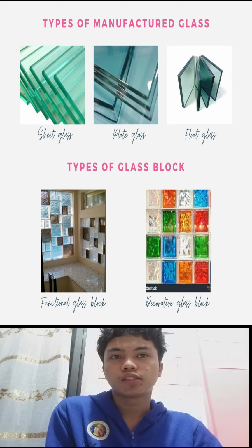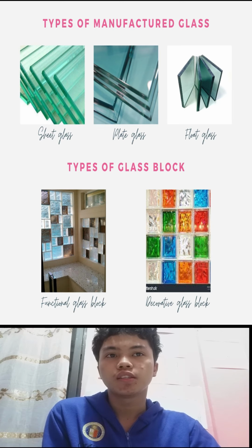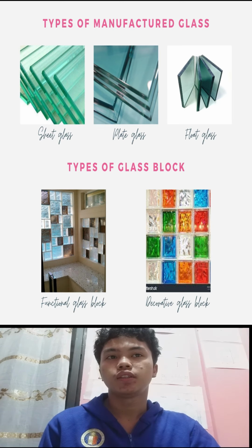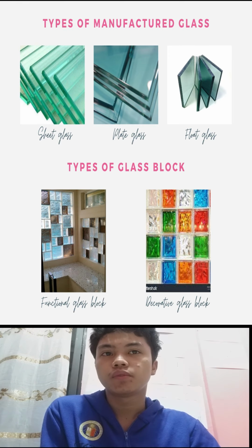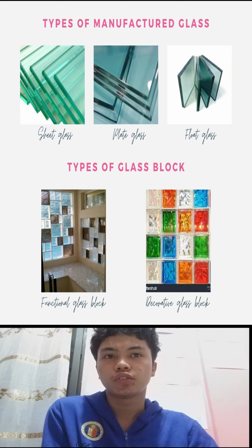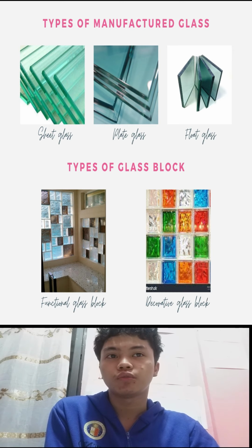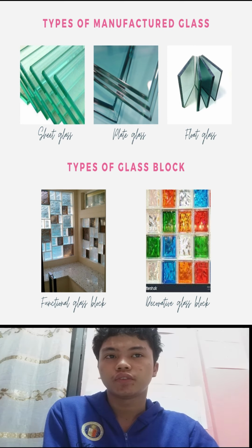The raw materials, which are sand, soda, and limestone, are first ground to a fine state and mixed in the proper proportions. This mixture, known as frit, is fed into the furnace and melted. Sometimes cullet of the broken glass is also fed in the furnace. This type of glass is used where vision is required but where cost is an important factor. The surface is good but never free from distortion, as the two surfaces of the sheet are not perfectly parallel.